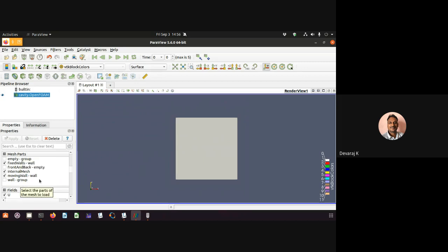I have extruded that. Now, if you come a little down, your pressure contour and velocity contour fields are ticked in. This is nothing but me trying to load the fields. I'm trying to define the geometry by loading the case file. So you're going to define the case and load it, then define the geometry. The geometry is displayed over there, and whichever fields you select, you will be able to see. Is that clear? Okay. Now once it is done, if you look at it, there are a few things, and I'm going to touch upon the very important ones.